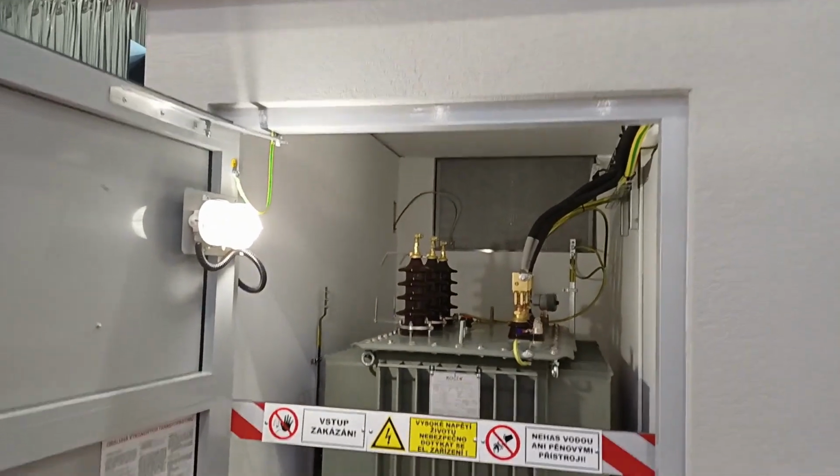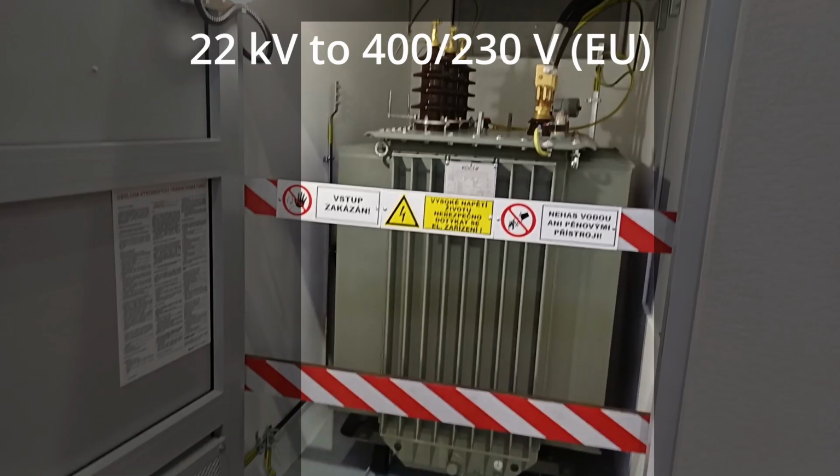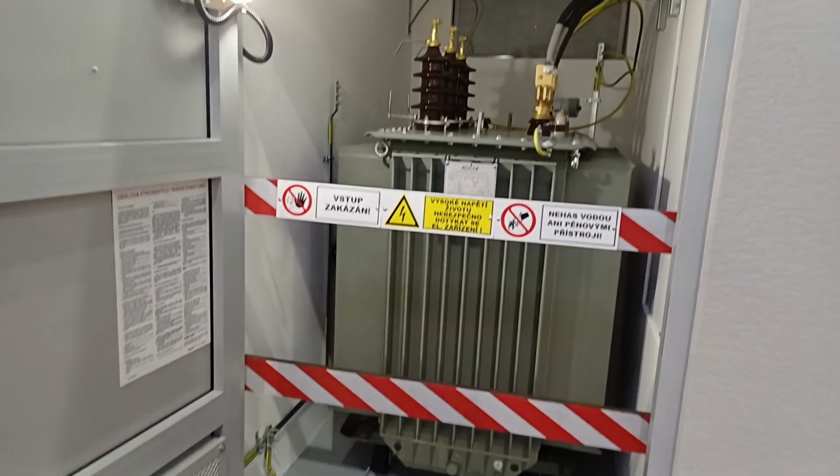This is where the key step happens. The transformer reduces voltage from medium to low, typically from 22 kV down to 400 volts. These are high voltage bushings. The transformer works on electromagnetic induction, and it also provides electrical isolation. This transformer doesn't supply a single house. It can supply entire streets, or even a full residential block.